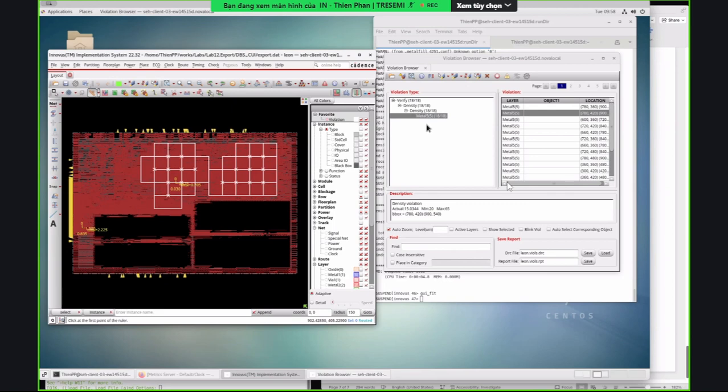Okay. Anything else you want to add? Yes. Ping mentioned there's a reason why we don't normally use Innovus to do metal fill. We all use a third party tool, to be exact Calibre, or some other tool. The reason is that each foundry per technology has a DRC rule deck, right? And what's in the Innovus implementation tool is not complete, it's not comprehensive.